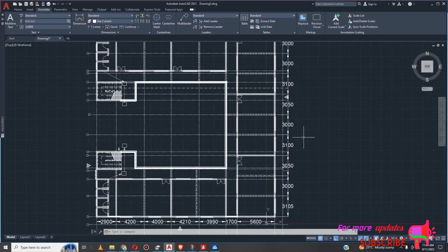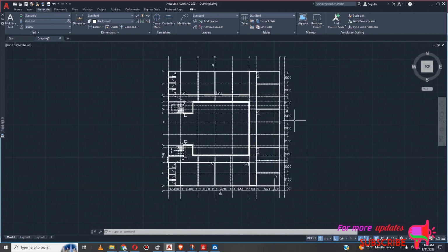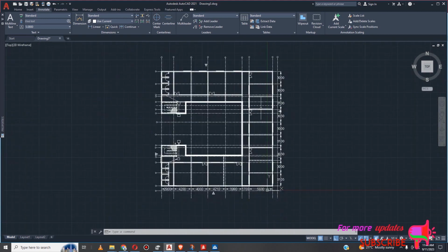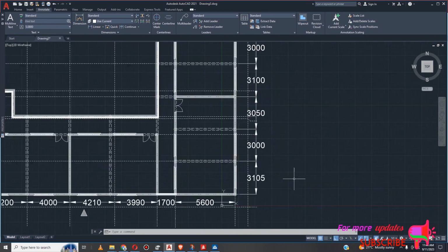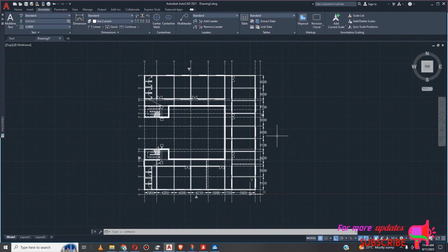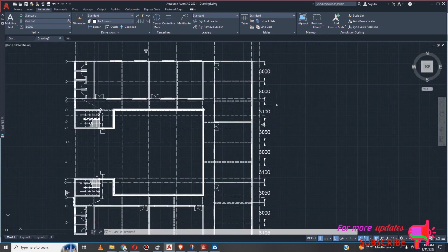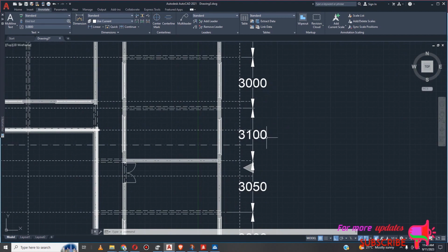So for this structure type, an experienced engineer would normally model halfway and design it halfway, and then mirror the design you find to the other half. That will enable you to work faster, and you will be more accurate because you'll be having a smaller structure to deal with. So that's why I can just modify my dimension to force that symmetry, all right?